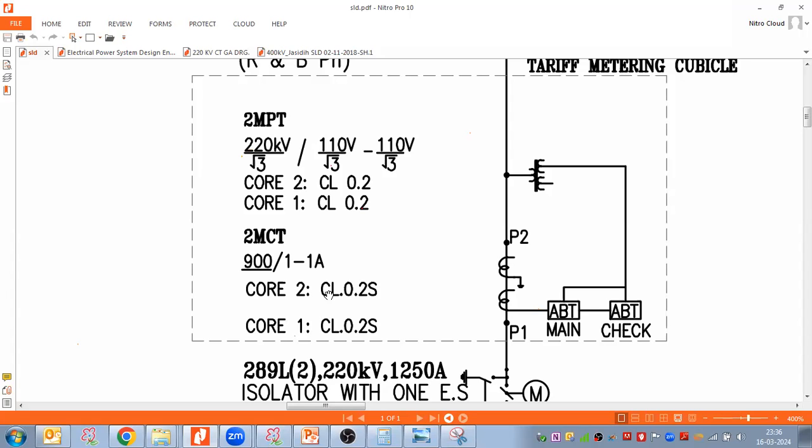My question is, the meter will never read any current once the CT gets saturated. Using the PX plus CT, how can your metering CT read the current? The purpose is actually to saturate, right? Otherwise, the meter will get damaged. That metering core should get saturated, that's why we are using that. Metering core will saturate for fault current and protection core will not saturate for fault current.